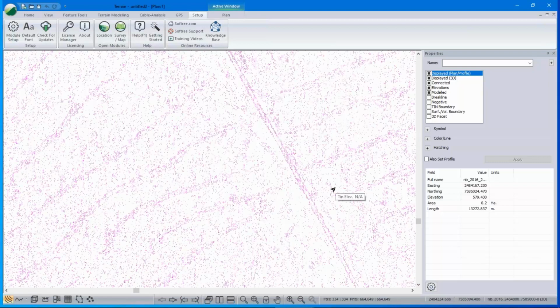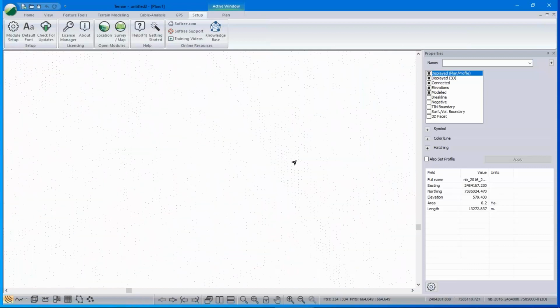It's quite common to see road features appear as dense areas in a raw LiDAR file, because LiDAR is a laser scan from an aerial device, aircraft or drone, and the foliage, trees can get in the way. So you'll see roads nice and clear because they are not underneath the canopy. But that leads to a problem with points. The scan lines here look like they're kind of going north-south. So it looks a little bit like a grid, but it's not really.